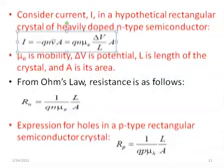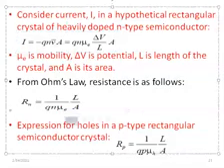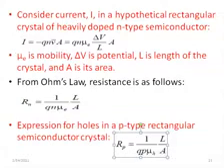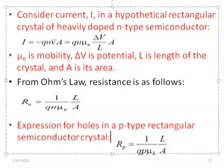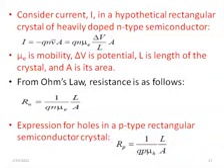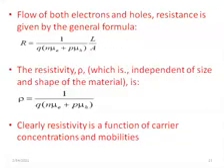You come up with this expression, which stands for the resistance for the n-type. You can have the same expression for the p-type, for the holes, which means this Rp is equal to 1 over Qp mu H times L over A. Instead of n for electrons here, we put p for the holes, and mu E should be replaced by mu H because we are dealing with holes. This is the expression for the resistance. And if you want the overall resistance from both the electrons and the holes, add these two formulas we talked about, and you come up with this expression.